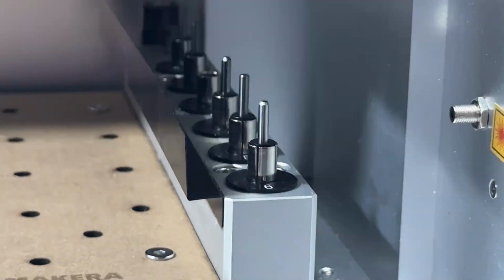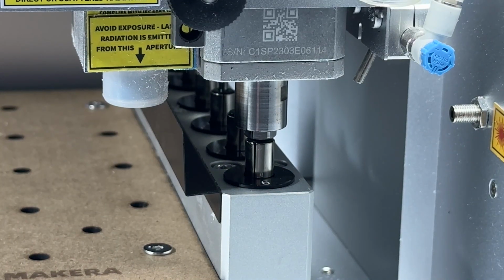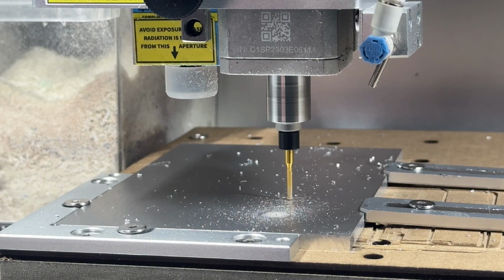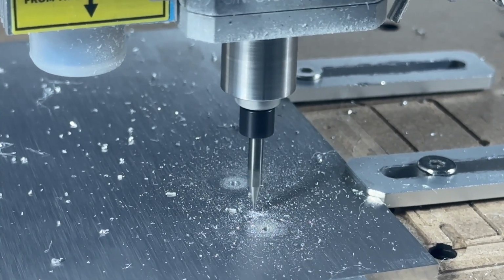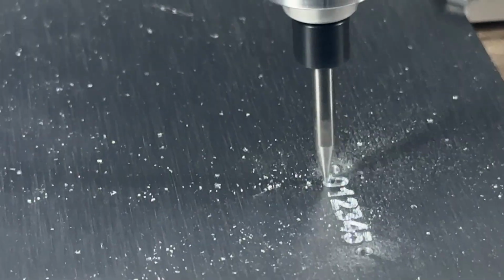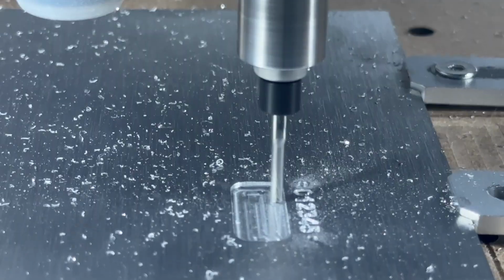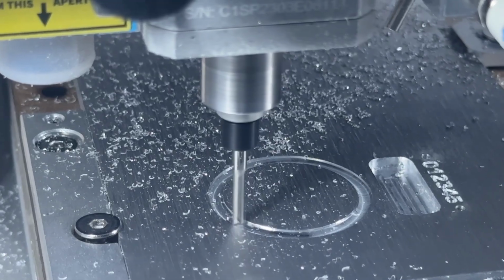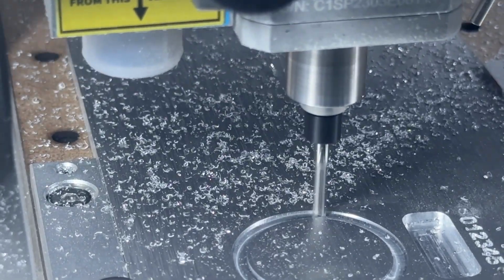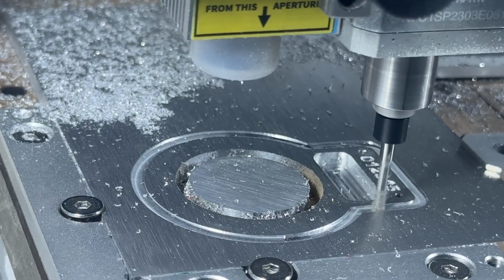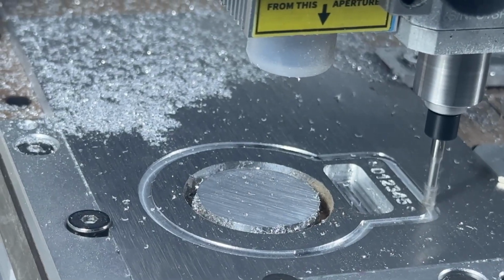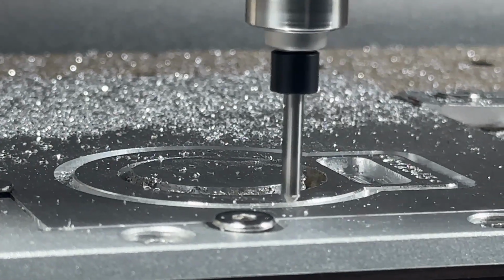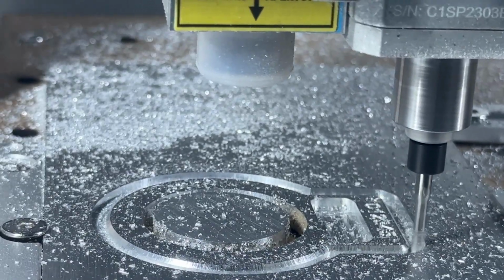After completing the scan margin and probing the surface, the Carvera will start to manufacture our part based on the toolpaths that were created. This starts with the peck drilling operations before machining the numbers in a pocket path with our engraving bit, then the larger pocket using our single flute end mill, then the larger hole using our single flute end mill before creating an outer perimeter cut, but that only cuts 3 millimeters down. The chamfering bit is then selected to create a chamfer before completing the outer contour cut.